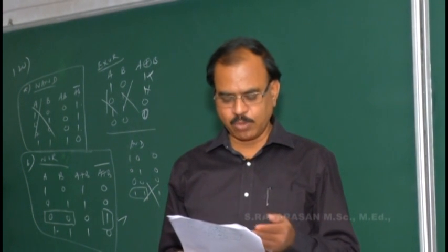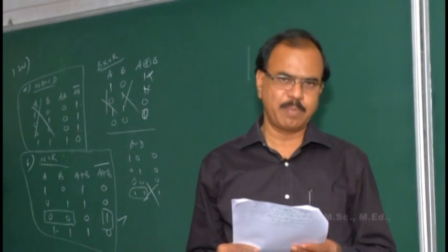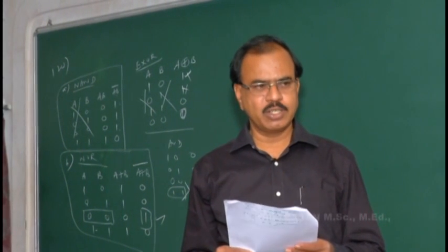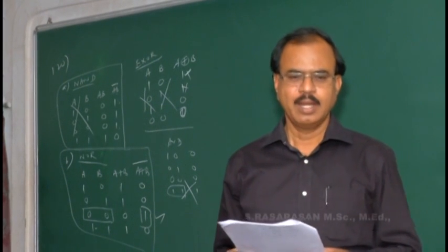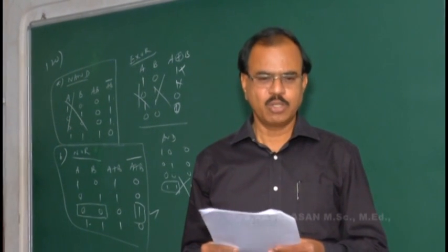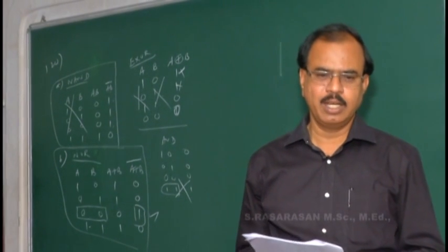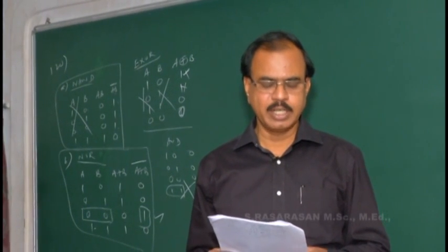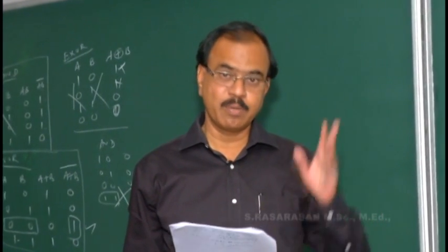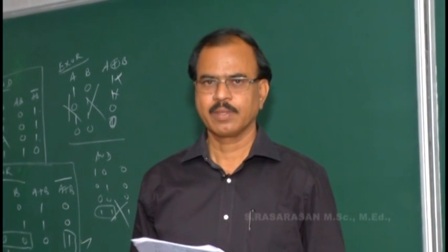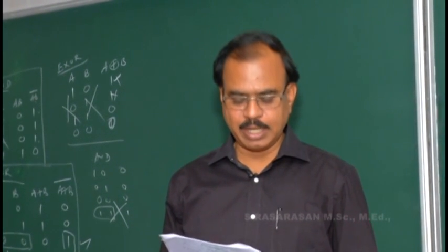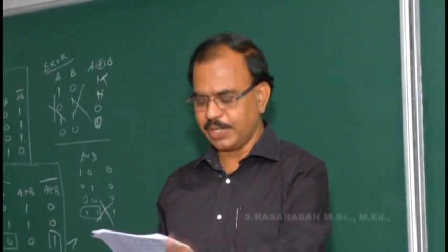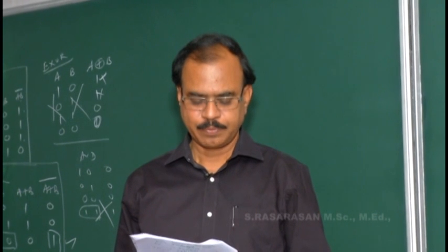Here horizontal deflectors and vertical deflectors are given. Synchronizing pulses must be given. A sawtooth potential given to the horizontal deflectors is called the line synchronizing pulse. A sawtooth potential given to the vertical deflectors is called the frame synchronizing pulse. So our home television receives both synchronizing pulses from the TV camera. The line synchronizing pulse must be given to the horizontal deflectors, and the frame synchronizing pulse must be given to the vertical deflectors.